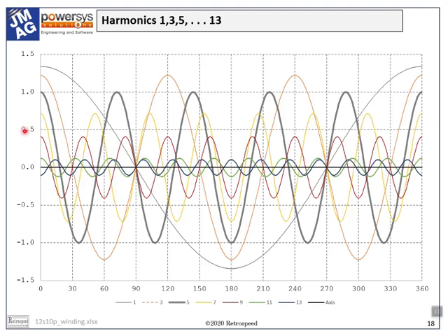The most crucial point to remember is that it's the fifth harmonic that locks into step with the rotor magnets. Mathematician's imagination or not, that is how it works. So this is a very, very practical, important engineering concept. Regardless of the mathematical complexity, it's that fifth harmonic which really counts in the operation and the production of the torque.